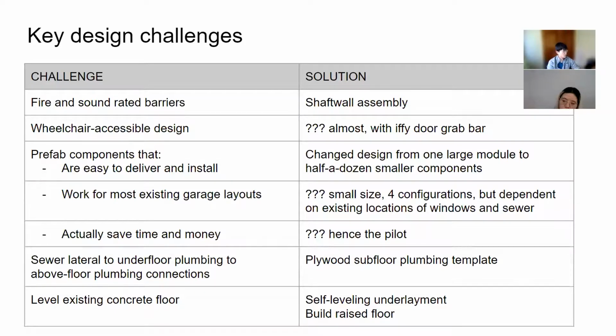And then for leveling the existing concrete floor, we think there are self-leveling underlayment products out there that you would do right before you bring in the big modules, or right after you set the core down and shim it into place, and then you level the rest of the concrete floor. On top of leveling, you would do floating vinyl floors, I think, as a standard solution that many of us do anyway for our own homes. So that's one solution, and we are going to try that for at least one of these projects.